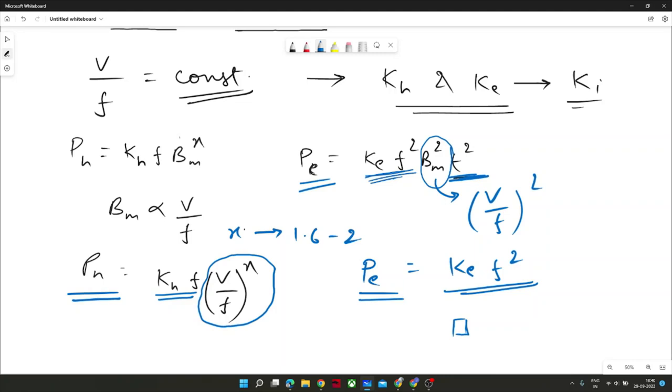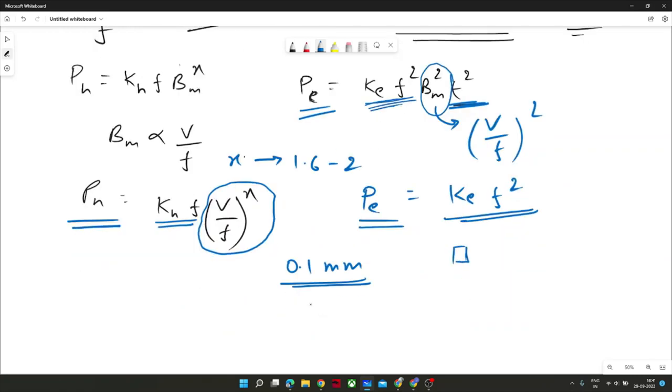But nowadays, since very high power, very compact motors and drivetrains are required, the minimum lamination steel thickness I have seen to date is 0.1 mm. And believe me, if I am going to design a motor for like 500 or 600 kilowatt, it improves the efficiency from 92% to 97%.